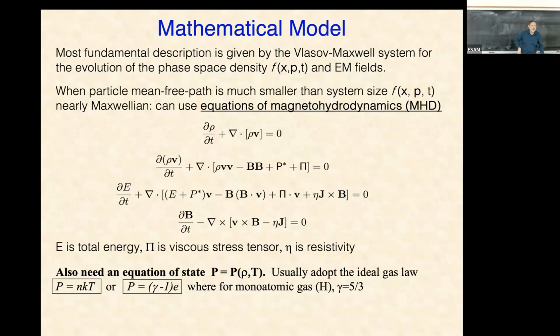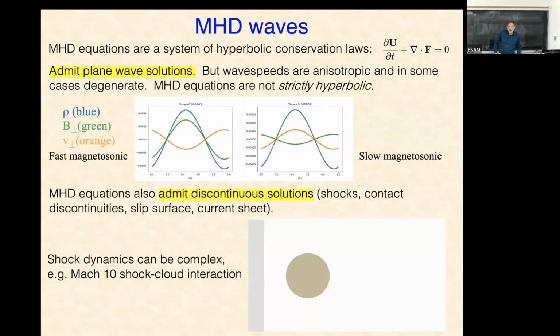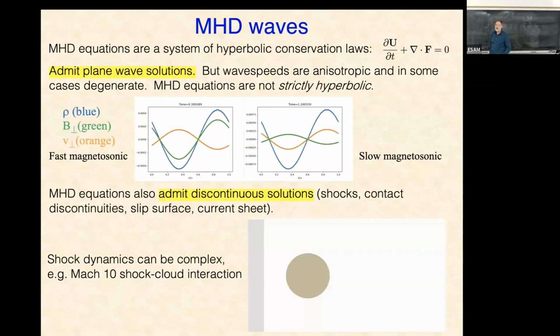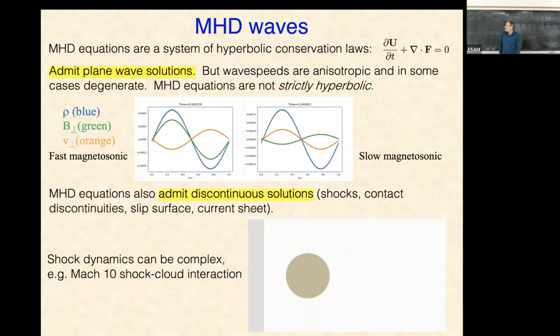So they should be sort of familiar. This is the same set of fluid equations that you know and love from terrestrial flows. The only difference perhaps is that these are compressible because typical flow velocities are usually much larger than the sound speed in astrophysics, and so you have to worry about compressibility. So we can use all the machinery and all the mathematical tools that we know about for these systems of equations to understand how to develop methods for solving them.